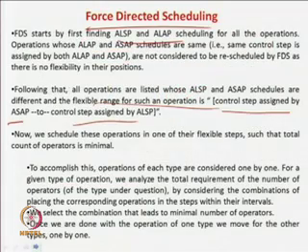Then we take each type of operation one at a time, like addition operations, then multiplication, then subtraction, then division, and try to freeze one at a time. What is the basic motivation here? Actually, an adder cannot do a subtraction, that is the assumption. In a very advanced paradigm, adders can also do subtractions, and they are actually the same elements, and multipliers can also be treated as dividers. So, sometimes we have general purpose blocks. But for simplicity here we are assuming that adders can do only addition, subtractors can do only subtraction and so forth.